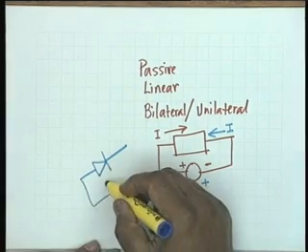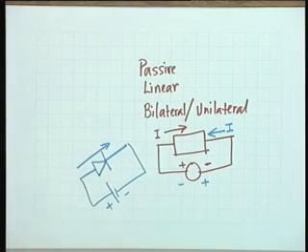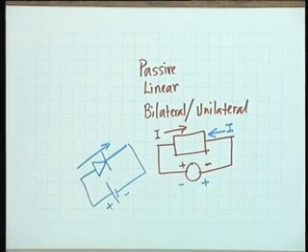That is, if there is a voltage source connected like this, it conducts as if it is a short circuit, an ideal diode. On the other hand, if the polarity of the voltage source is reversed, then it acts like an open circuit. The current almost reduces to zero. The diode is an example of a unilateral element.